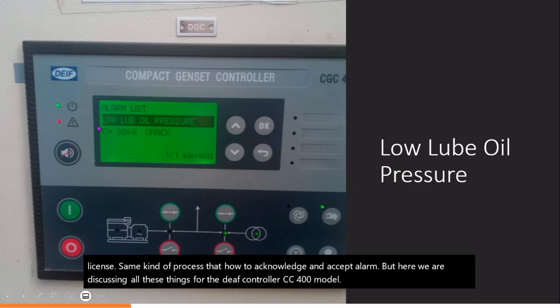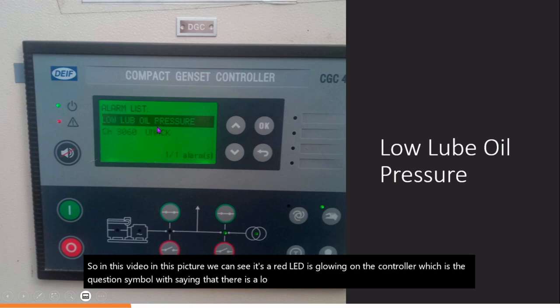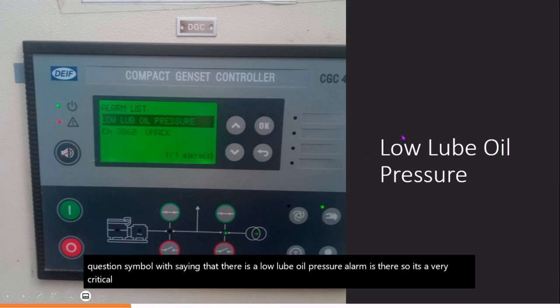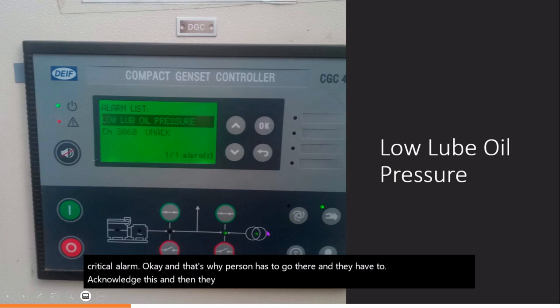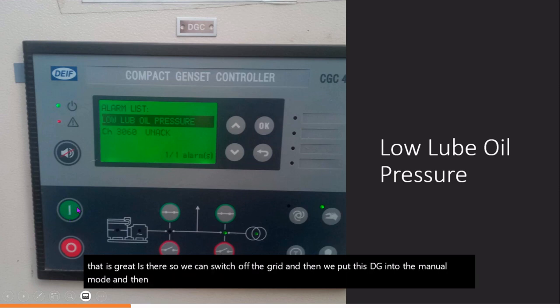So in this video, in this picture, we can see a red LED glowing on the controller, which is a caution symbol saying that there is a low lube oil pressure alarm. So it's a very critical alarm, and that's why the person has to go there and acknowledge it, and then they can switch off the grid if the grid is available. Like here we can see that the grid is there, so we can switch off the grid, and then we put this DG into manual mode, and then by pressing this green button, we can start the engine in manual mode.